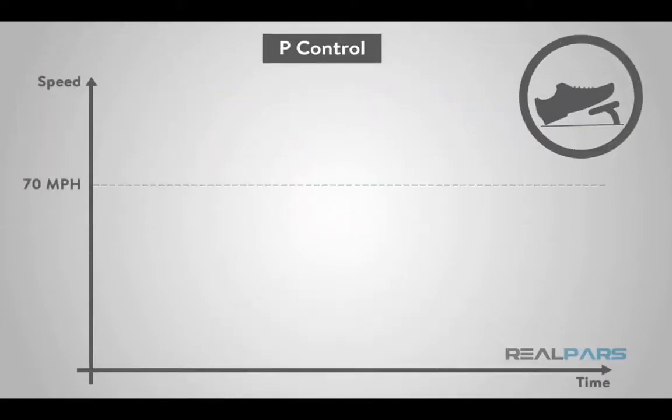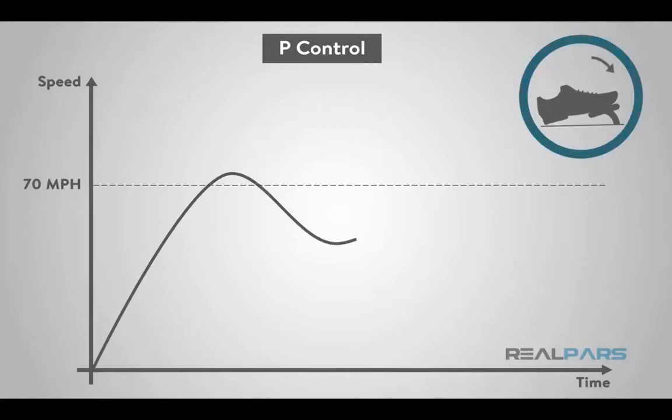And just as a PID functional refresher, using the car cruise control as an example, the P, or proportional, is described as: the farther you are from the desired speed, the more you press the gas pedal, and the closer you are, the less you press on it. This works well, but when you get to the desired speed, based on this rule, you would let off the gas completely. The end result is your car slows down and stays a little below the desired speed. Proportional control is the main ingredient of any control, but may be a little inaccurate.